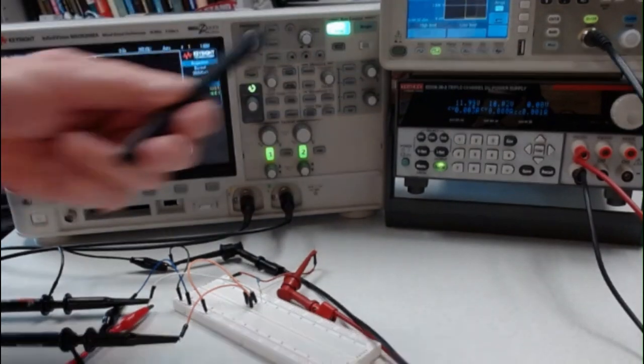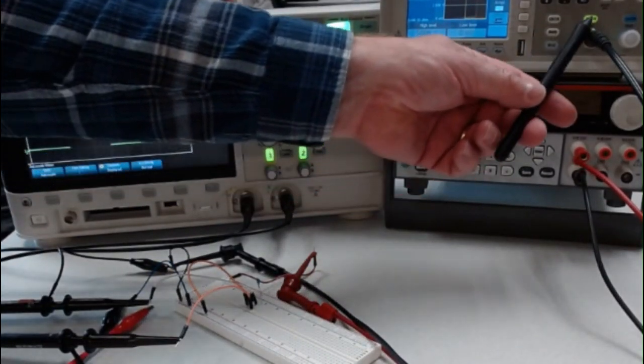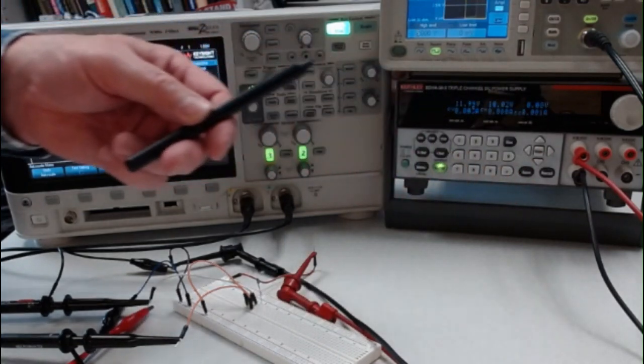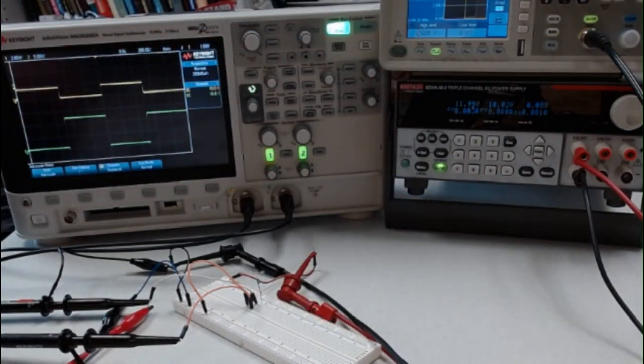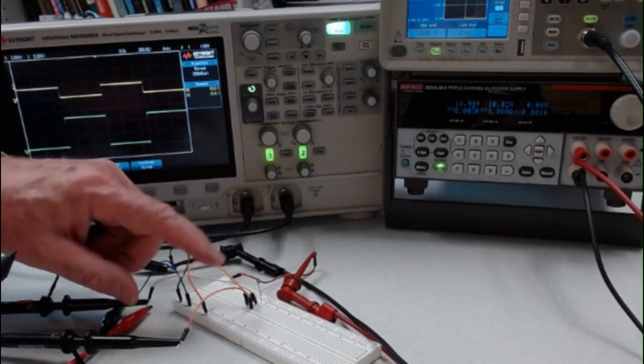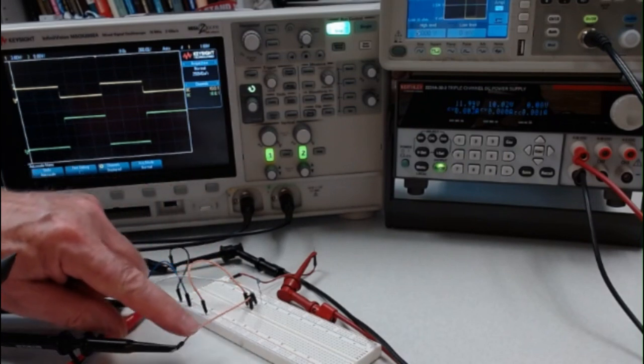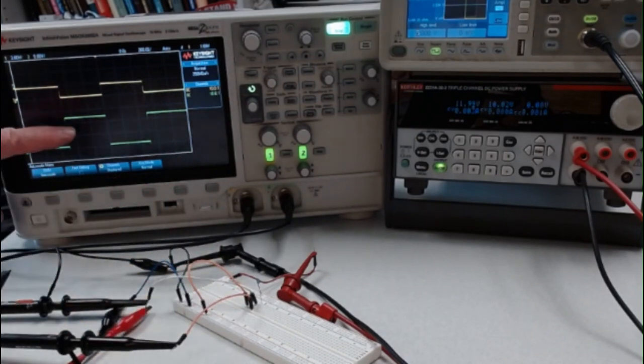I've got the base connected directly to the frequency generator over here. So this is coming directly out, and it is set at 5 volts, but it doesn't really produce 5 volts. It's at 1 kilohertz, and we're going to look over here at the scope in a minute, it's producing about 2 volts. But I want you to notice what's happening, because the emitter coming off of here comes over to the green in the output, and this is the first time you've probably seen this, where we're actually amplifying a circuit.